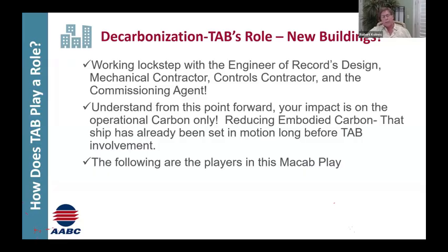But if we have the opportunity to work with the engineer early on as part of the design team, then we can communicate having our AABC specifications as part of the project manual, because it's within our specifications that our national standards for total systems balance are defined. And then in preparing a plan review for balanceability, it's essential to use the plans, the specifications, and cross-reference with the submittal data.